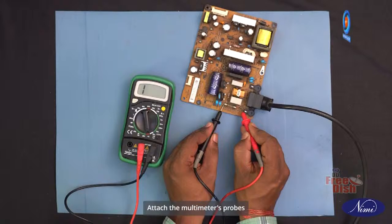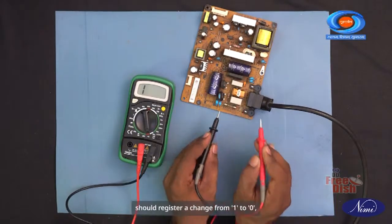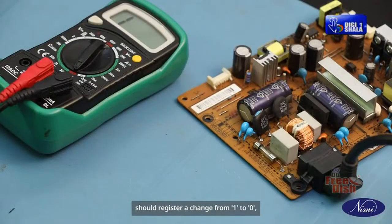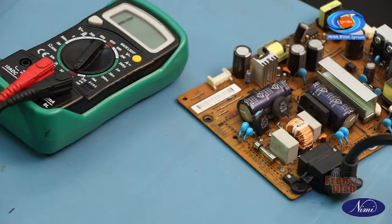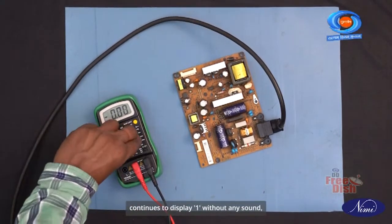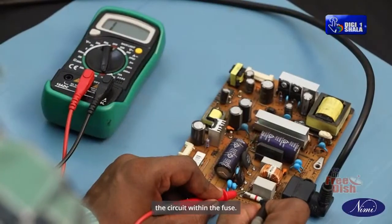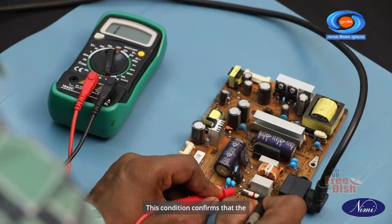Attach the multimeter's probes to both ends of the fuse. In a functioning fuse, the multimeter should register a change from 1 to 0 accompanied by a beeping sound indicating continuity. However, in our scenario, if the multimeter continues to display 1 without any sound, it signifies a break in the circuit within the fuse. This condition confirms that the fuse has blown and needs replacement.